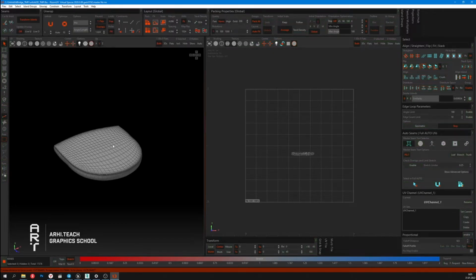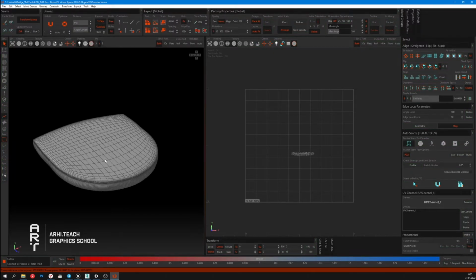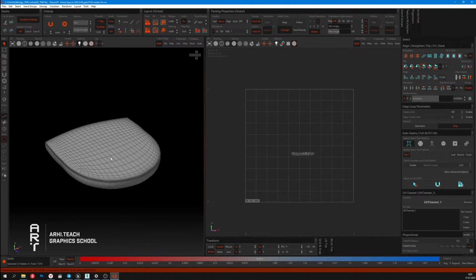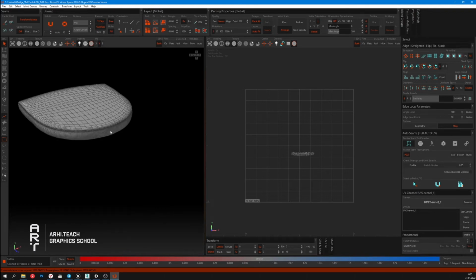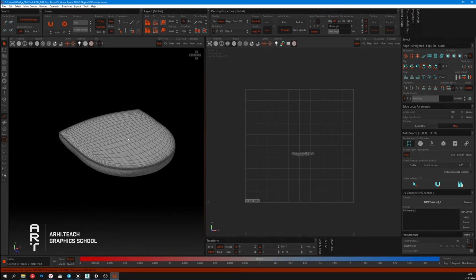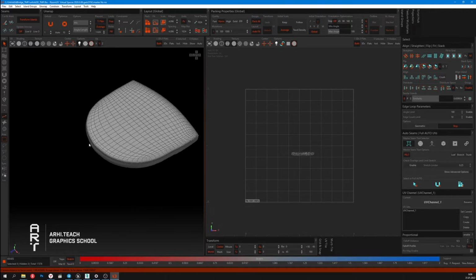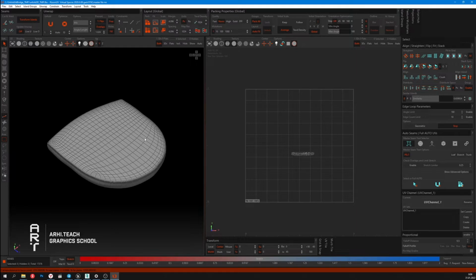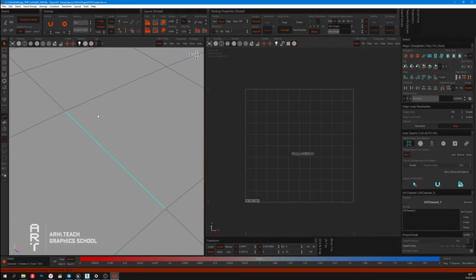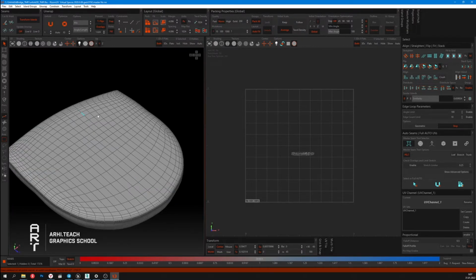The navigation works in the following order. Scaling using the mouse wheel. We can move the model by pressing the mouse wheel. In order to turn the model, we use the Alt key. You can also use the hotkeys for navigation. The F key lets you focus on the chosen segment. The A key lets you focus on the whole model.